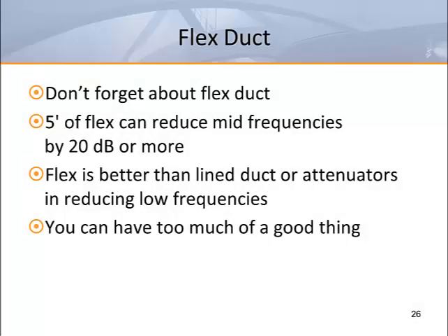And don't forget about flex duct. When flex duct is properly installed and managed, it can make a major reduction in discharge sound levels. The important thing to remember is it should be no more than 3 to 5 feet long and should be properly supported to create a proper inlet condition for the grill or diffuser being supplied.